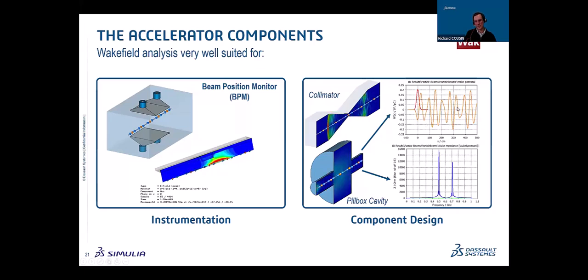And if you do a fast Fourier transform of this signal, then you can directly analyze if you have any mode competition and so on, which would also affect the whole acceleration process for the structure. So this can really be fully analyzed, and you can do some virtual prototyping in order to really design the accelerator component properly.